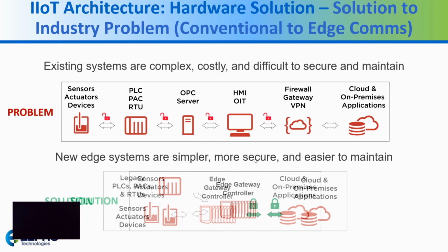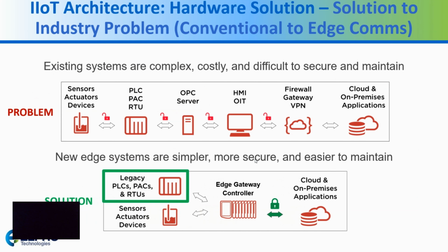The latest solution would use MQTT, which would be collecting the information from those PLCs or sensors directly into a controller or gateway, then built into the gateway's configuration, able to add security to have a secure connection to the cloud using TLS certificates.